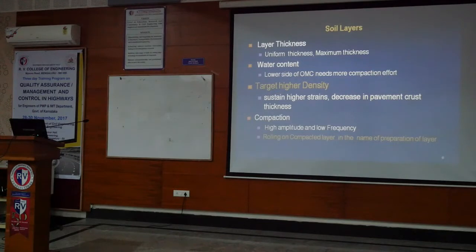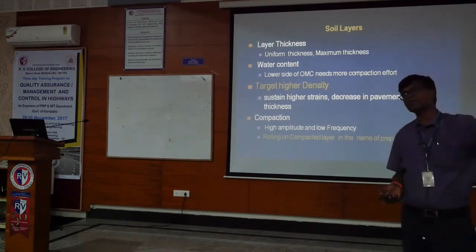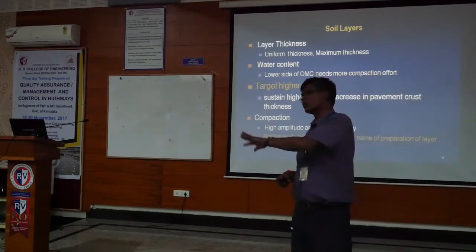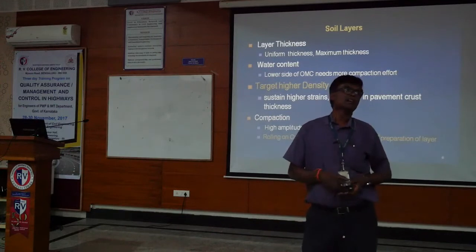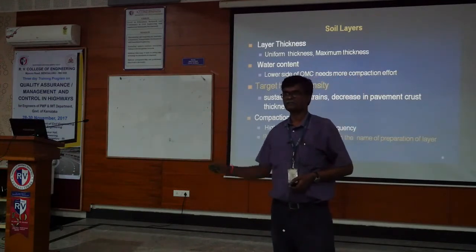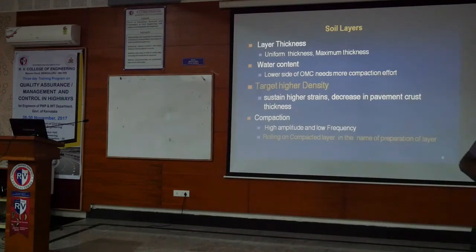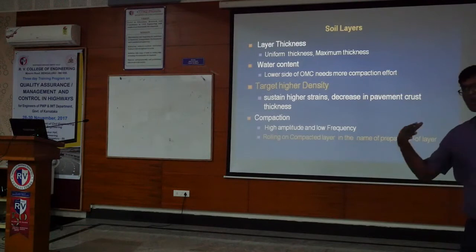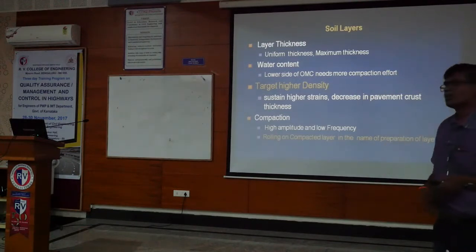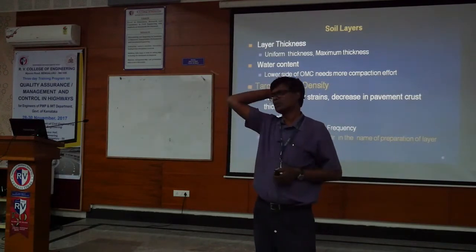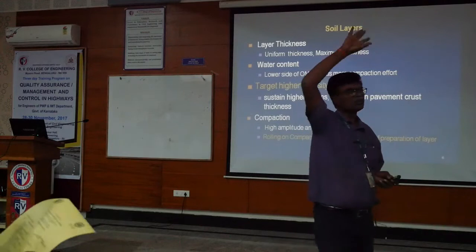So it is a fact that only at a particular water content for that material can we have optimal, highest density. So when we are not doing this, if we put more water content or less water content, we are not optimizing that soil material. So that's one. And the vice versa, the other part of this is there is no water available. Then how can I use that 9% OMC? It runs into several thousand liters. This is a huge quantity.